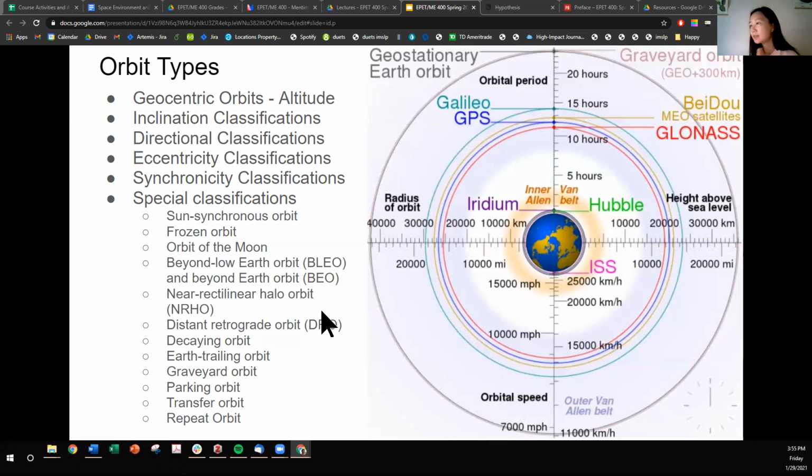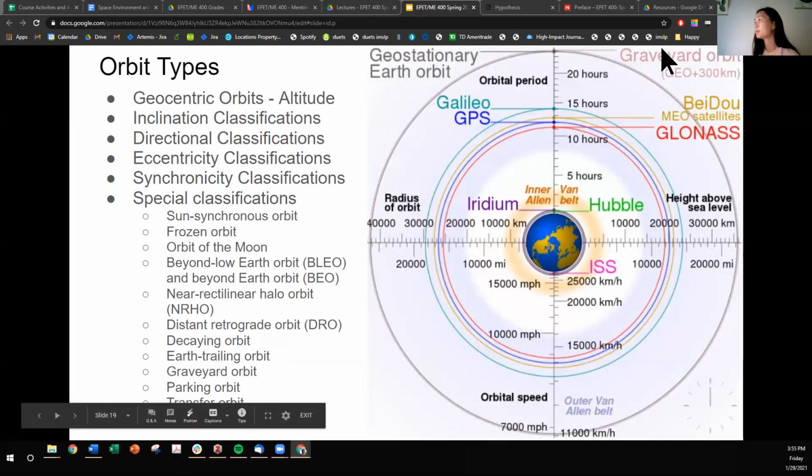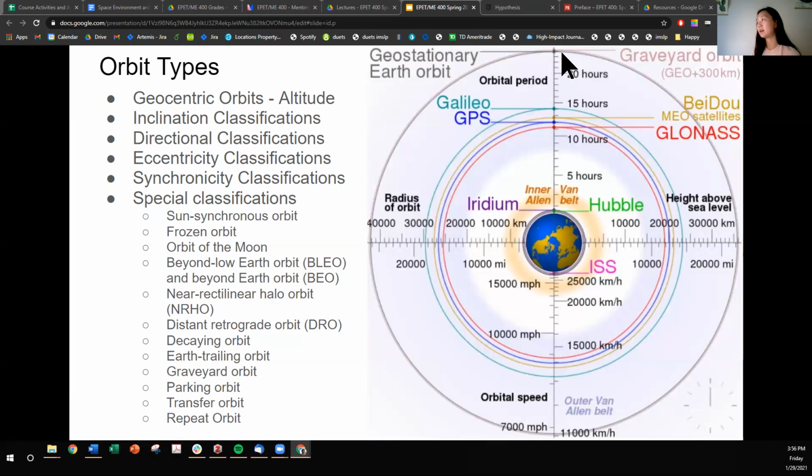So yeah, maybe some notable orbits. There's something called a graveyard orbit, which is just beyond geostationary orbit. Because communication satellites are so far away, to dispose of them, to have the end of life mission, you need to allocate an orbit for them to be discarded. So the geostationary satellites will have a little bit of reserve fuel left so that they can boost their altitude to this graveyard orbit, where they can rest in peace.